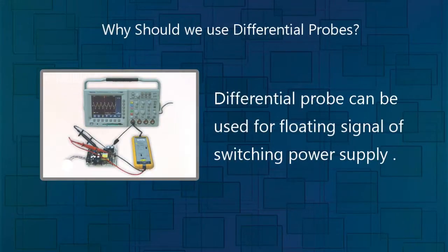Why should we use differential probes? We all know that probes must be used while using an oscilloscope, due to the speed of semiconductor components, which becomes faster and faster. The signal frequency of the circuit under test is becoming higher and higher. Today, to acquire the signal from the circuit under test, and transport it to the oscilloscope correctly without any effect on the circuit operation is definitely not an easy task. Using the correct probe is the key. An incorrect probe will render any expensive oscilloscope useless.